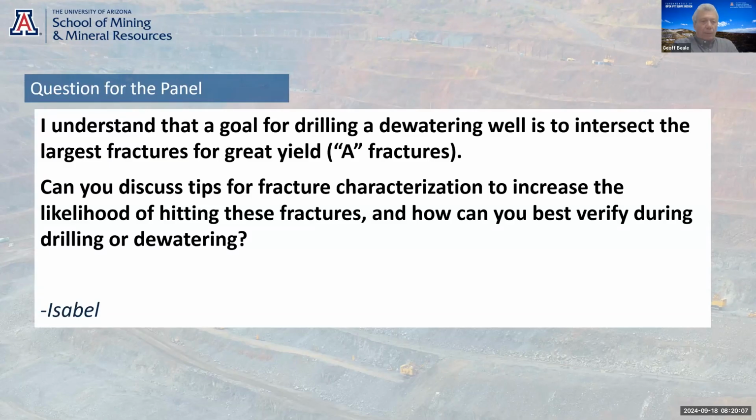But there's an example I had from several years ago of a site which was putting in wells which were about $3 million each, and they just got consistent fractures every time, so they dropped the idea of a pilot hole, and then lo and behold, they drilled a dry well because they hadn't put a pilot hole in it. So really, there's no substitute for pilot hole drilling.